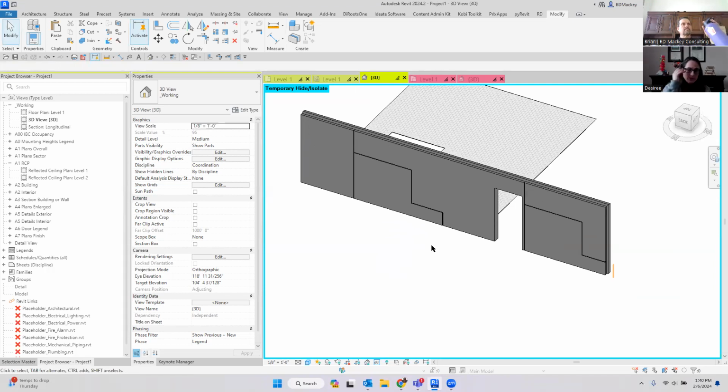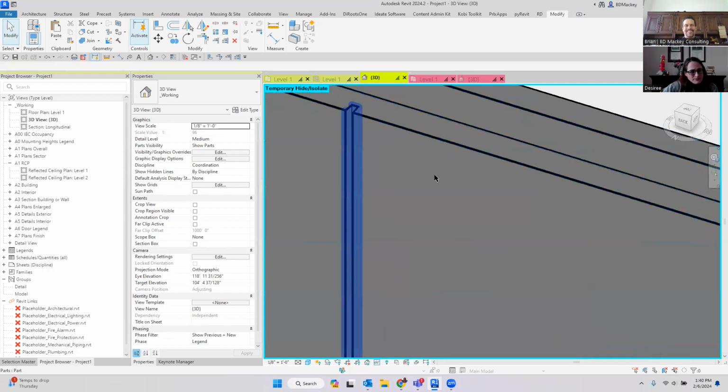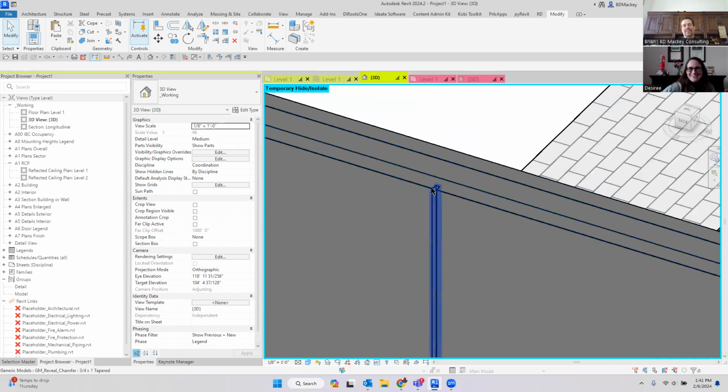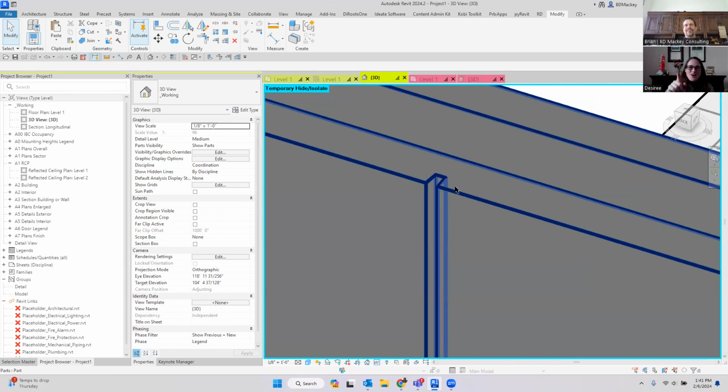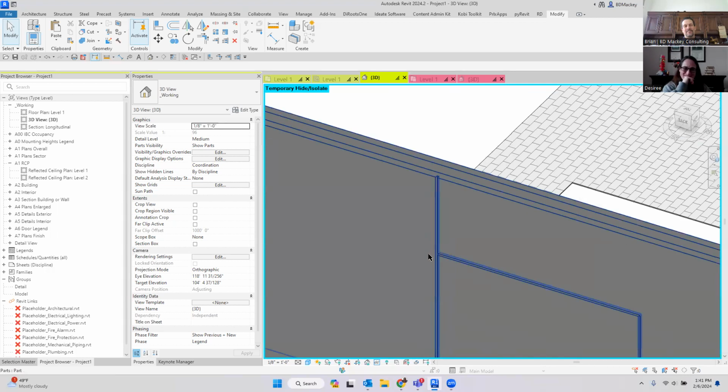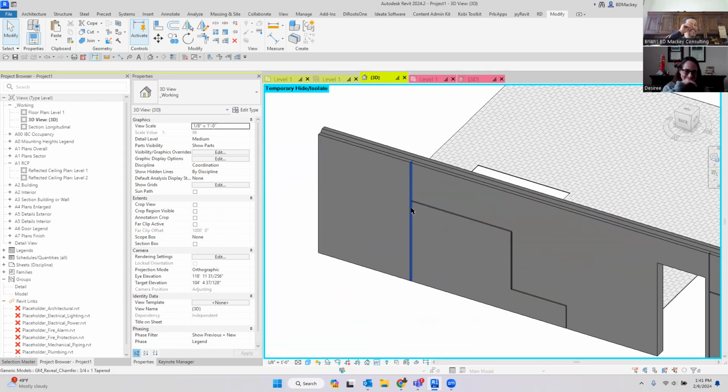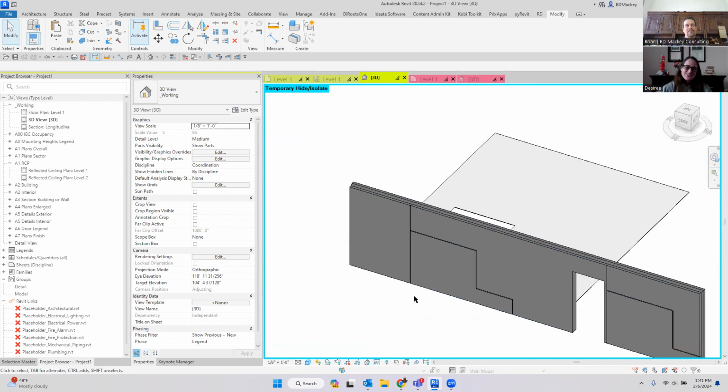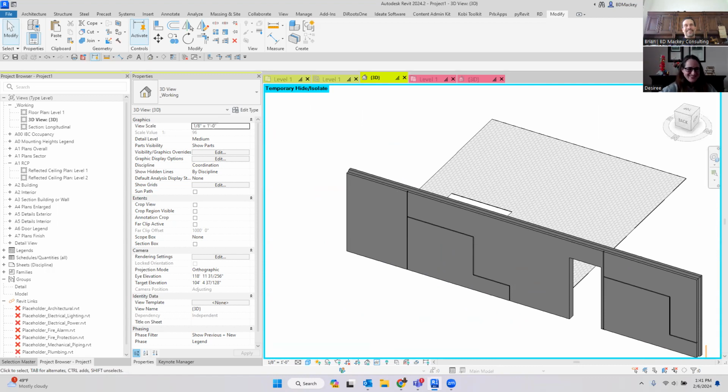Once you start talking about reveals and concrete walls, I just think about how much bigger my rebar has to be because you just cut out my cover. I don't know, it always makes me crack up when I see engineers say 3-inch minimum and then they draw this. You realize that entire wall is now that distance reveal thicker to get the cover for the rebar. Yep, nope. I always laugh at that. I see it and I'm like, yeah, this doesn't physically work. Because you've got this 2 inch. But I'm glad you guys think it looks pretty.